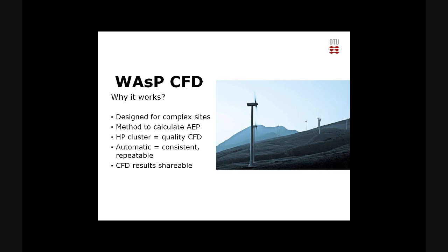You can get more wind data input and your CFD results are still valid. So it's another way of working with CFD results than we're used to. It's only if you change your map details, your topography, then you should redo your CFD simulations. Otherwise, they are still valid.